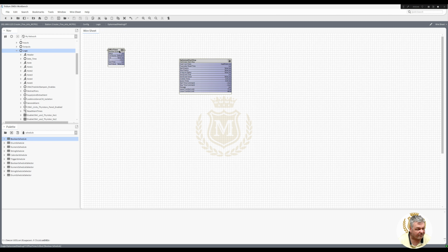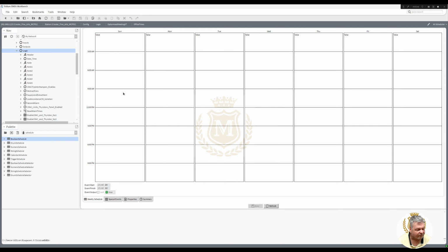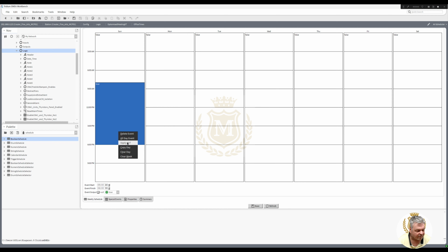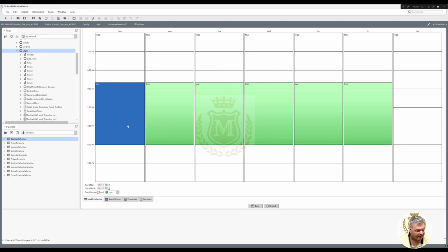We need to put in the times of when the office is occupied, not before. So you wouldn't go from 6 AM to start the heating, you do it from the time when you want it to be on. So let's say 8 o'clock. Well, we're not going to be working on a Sunday, so I'll delete that in a minute. 8 while 6, apply Monday to Friday, get rid of that one, delete.